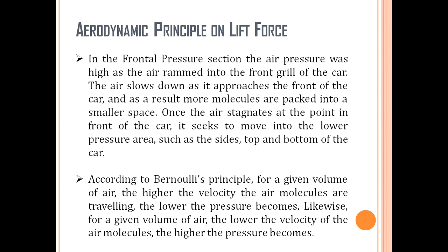So the pressure of the air molecules will be increased here. And once the air stagnates at the point in the front of the car, it seeks to move into the low pressure area, because we know that fluid always tends to move from the high pressure region to the low pressure region.